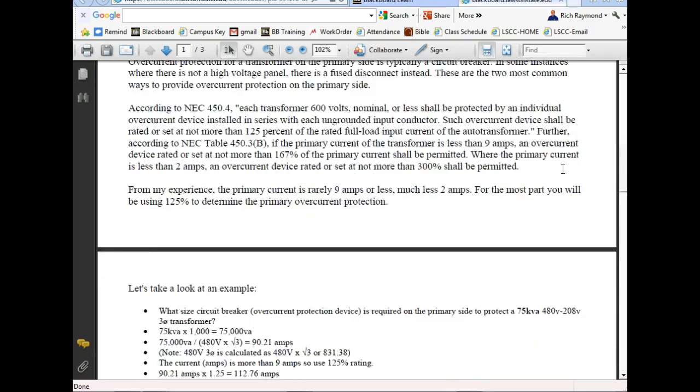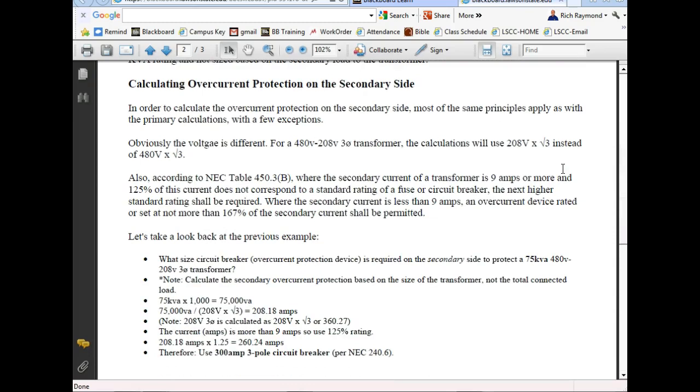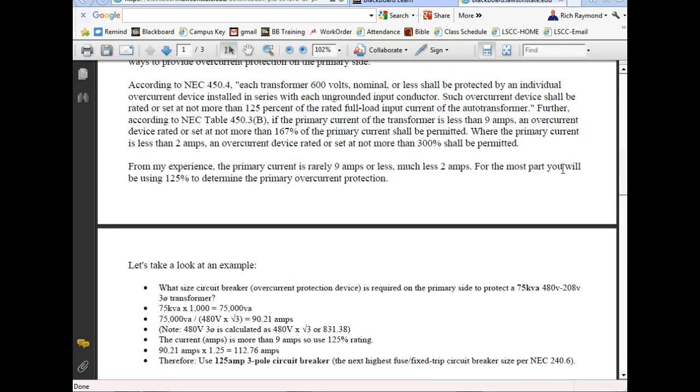Now if we fuse the secondary, and of course the best thing to do is to fuse both sides, right? So the primary, and this is why you need to understand power. To calculate the primary current, what you need to do is use power, right? Y'all understand? So I is equal to P over V, right? Everybody understand that? So I've got a 15 kVA transformer over here. We're going to calculate it in a second.